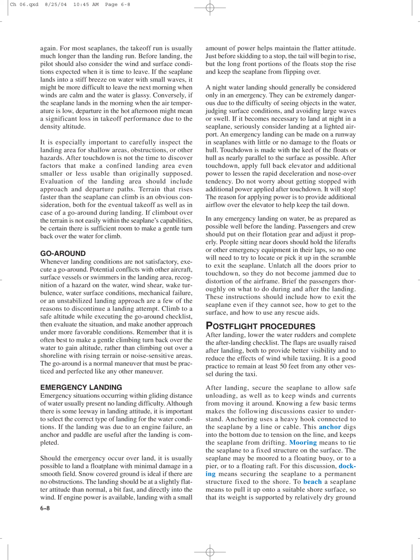A night water landing should generally be considered only in an emergency. They can be extremely dangerous due to the difficulty of seeing objects in the water, judging surface conditions, and avoiding large waves or swell. If it becomes necessary to land at night in a seaplane, seriously consider landing at a lighted airport.